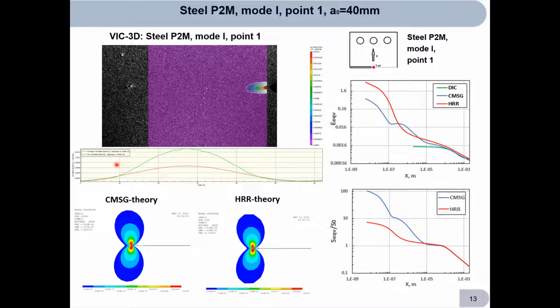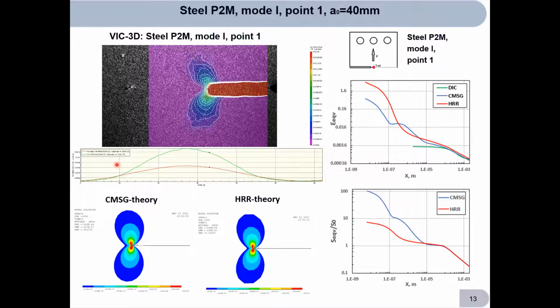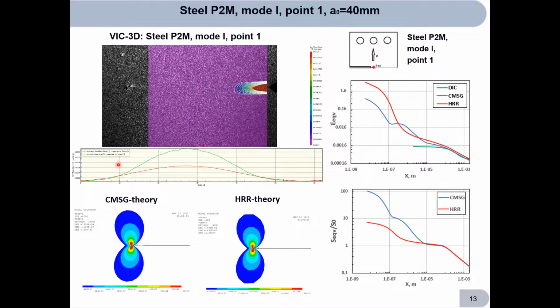The first contours were obtained during the testing of CTS specimens using the Vic-3D complex. The video shows a recording of one loading cycle. The lower figures correspond to the results of numerical calculations by the finite element method in the framework of classical and gradient theories of plasticity. All results are presented in a single range of values. As we can see, visually the shapes of the contours of the deformation fields are identical to each other.